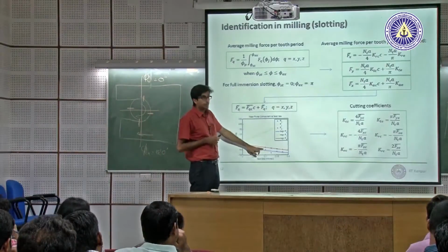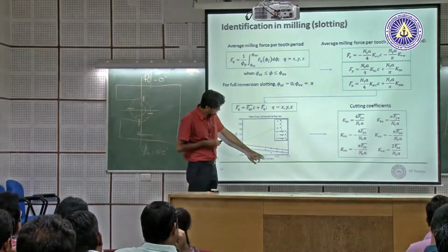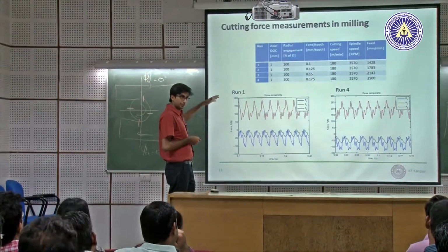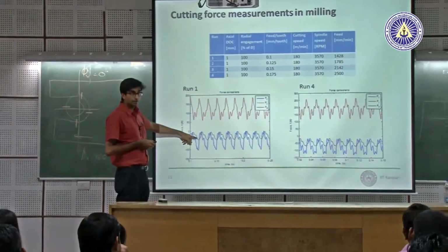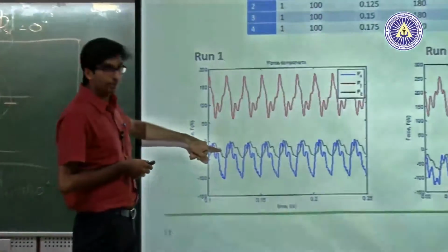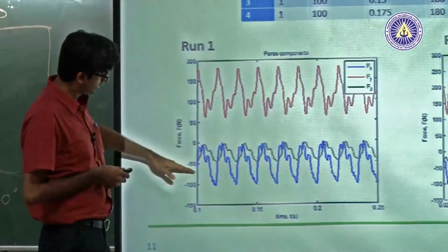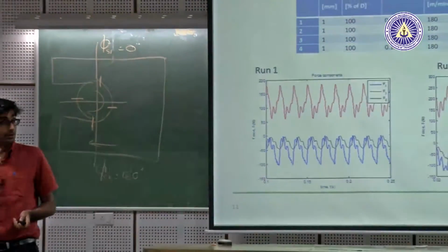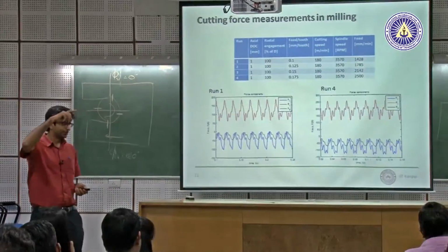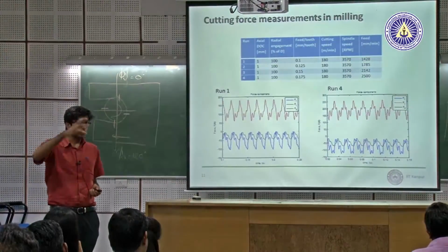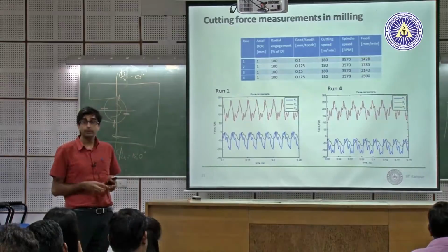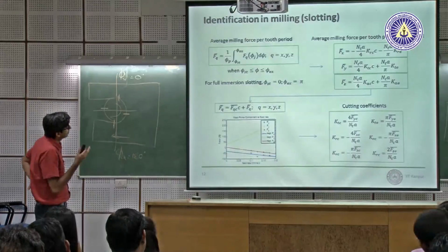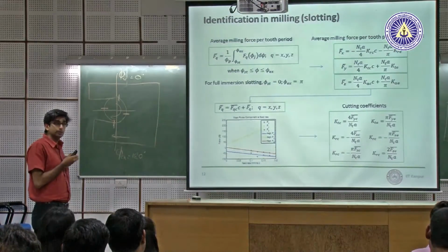So if, for example, at this feed, let's go back and look at that figure. So axial is Z. Z is the dark black line. So it's actually just 25-30 Newton, whereas the average for X is 80 Newton. Because this is an end mill. If it was a ball end mill, or an inserted end mill with a round insert, then the axial component will be very, very high. But this is an end mill. Okay, so we did this fitting and we got coefficients.